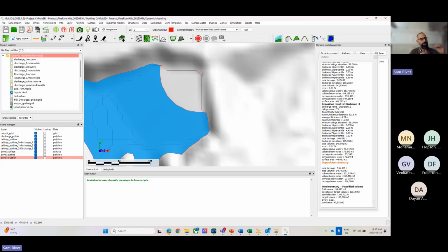And then the remainder of the 150,000, it deposited from the second location. But we know it takes 208,000 cubes to fill this completely to one elevation. So essentially, I have less volume than I did previously. So it can't place both pour points up to 113. So it places this one to 113, and this one's lower.